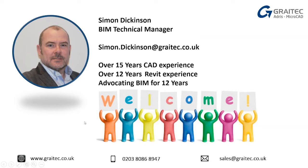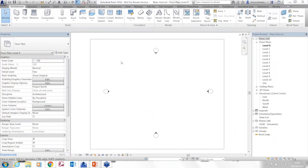Okay, so let's start to have a look at some of the tools that we've got actually in Revit. I'm going to start out from scratch on a blank drawing, and the first thing I'm going to show you is that we've actually got energy analysis tools now built into Revit that not only work further down the line on the actual proper building model itself, but we can start from a very early stage in the project. In this case, I'm going to do something from a conceptual point of view and show you the conceptual tools that we can use to start to get a feel of how our building is going to perform.